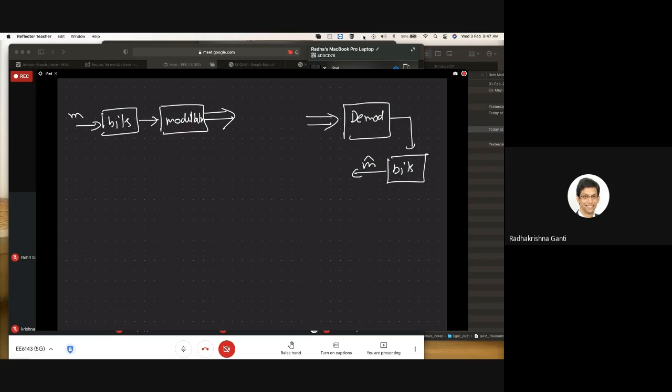The first simplest channel that we are talking about is called additive white Gaussian noise. Effectively, noise gets added here. Instead of worrying about what happens in the RF and other things, we make a simple model. This is the most important model. I am not worried about the RF, because there's an up converter in the transmitter and a down converter in the receiver, and these two cancel each other. Effectively, noise gets added. This is also a complex noise, because you have I and Q, which is a complex number, so you add complex noise. This model is called the additive white Gaussian noise, AWGN, model.